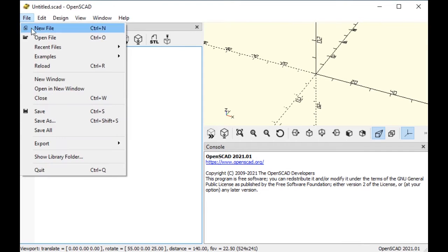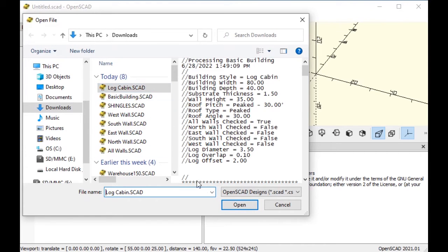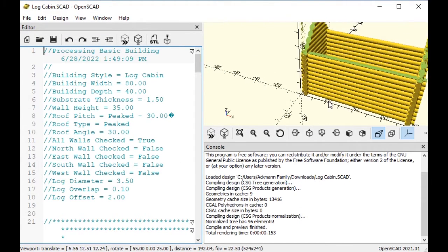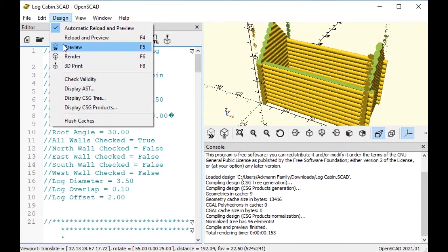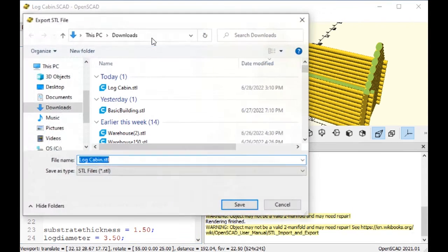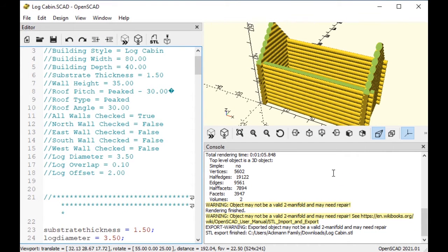All you need to do is load the generator files into OpenSCAD, render them with the F6 key, and save them as a stereolithography file, a 3D model. You then have a model you can print immediately or enhance further with a traditional CAD package. I have done all the programming for you. All you need to do is design, convert, print, and enjoy.